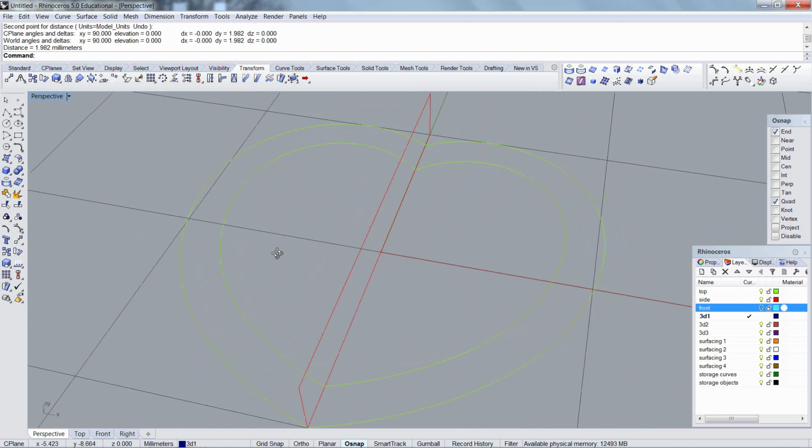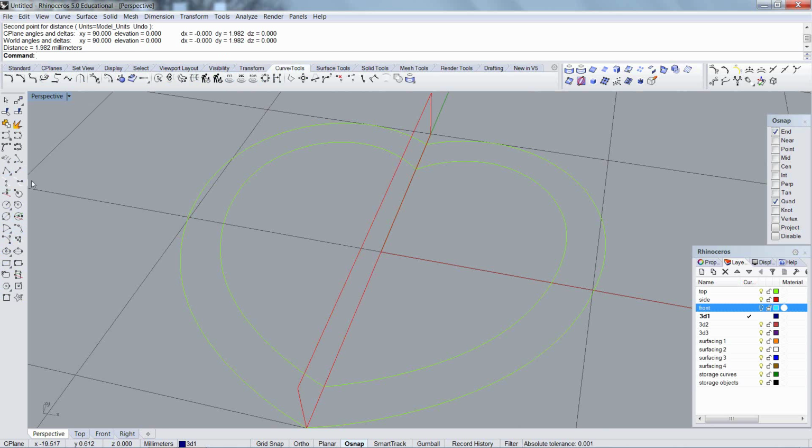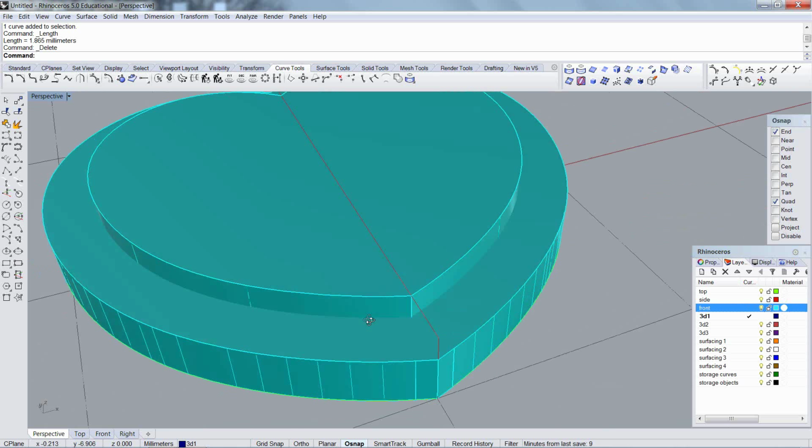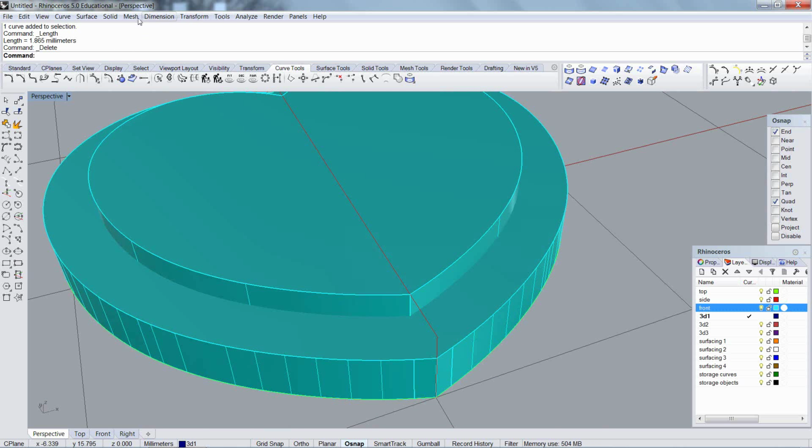I have basically 1.9. That's really not accurate because it's at an oblique angle to the two curves. To get it accurate, I would need to do this, and we'll see what the difference is. Length of that curve is 1.865, so 1.9 is fine. So I can fillet it at 0.8, or just under 0.8. So solid fillet edge. 1.8 would actually be 0.9, so I'll do 0.8.